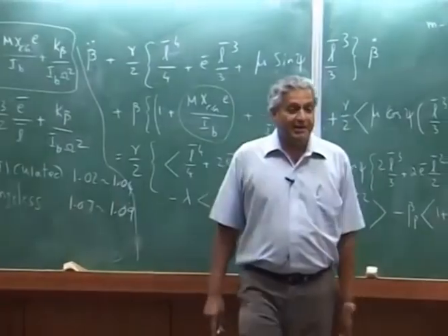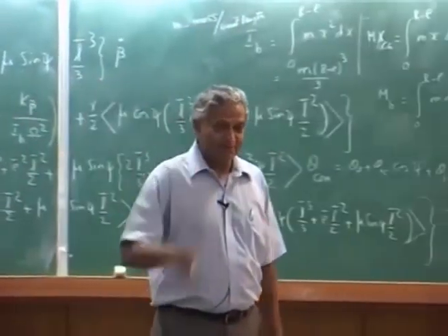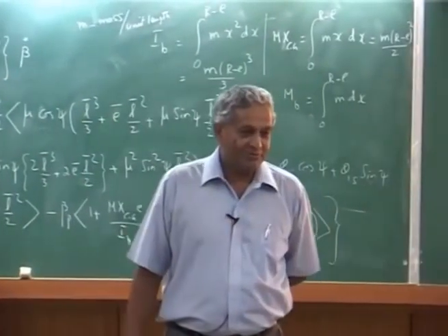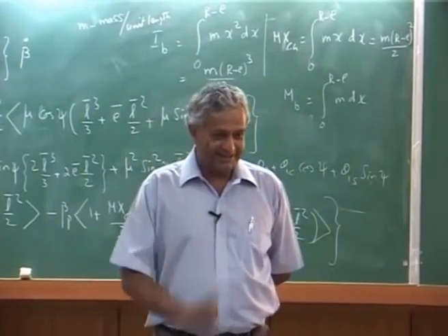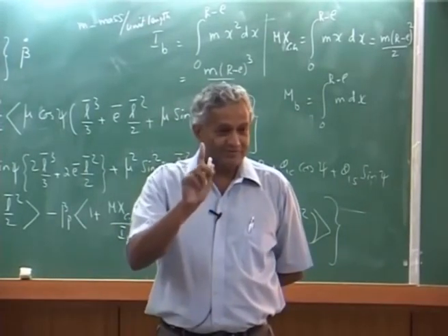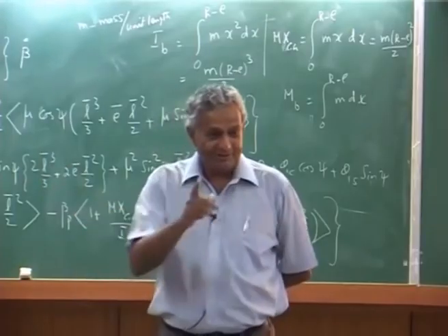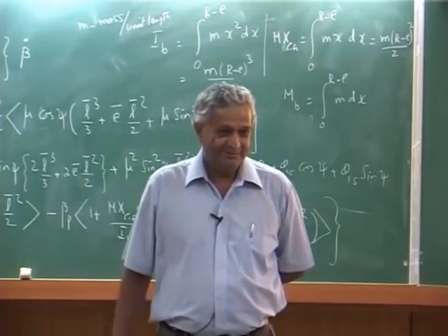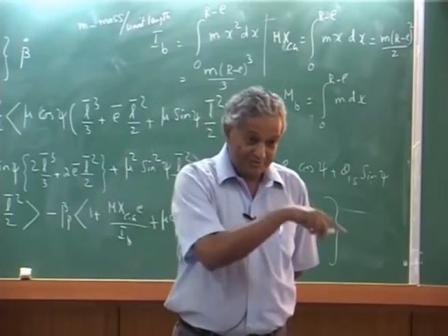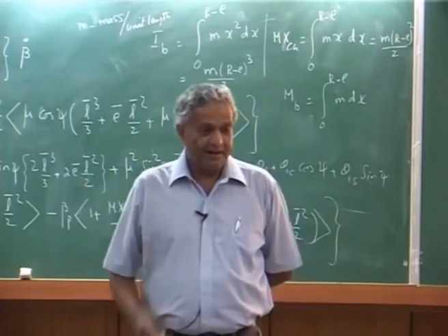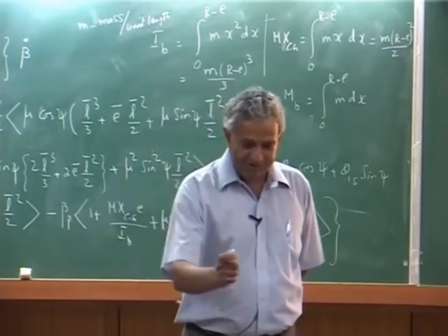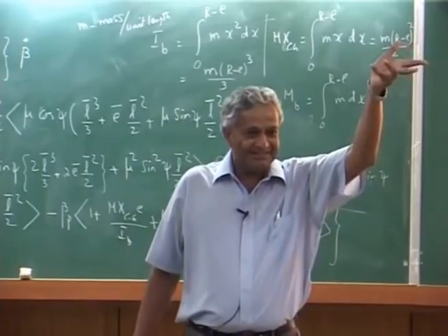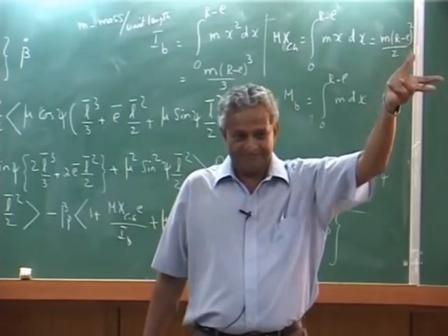You remember Cmx, Cmy, that expression was (Omega bar Rf square minus 1) divided by gamma by 8. If Omega bar Rf square is higher, you get a higher moment, right? Higher control moment means the pilot, for a unit stick motion, gets a large moment.